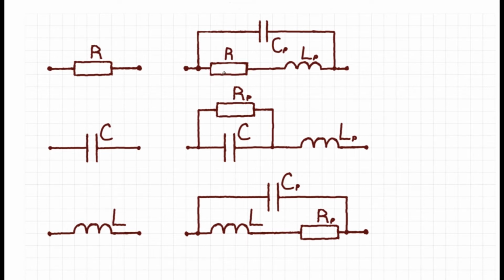On this circuit we see the resistor itself, and there arose parasitic values, or parasitic elements, such as capacitance and inductance with the little subscript letter P. Okay, capacitance has arisen between contacts of the resistor because with high frequencies there arose currents of displacement between contacts of the resistor.